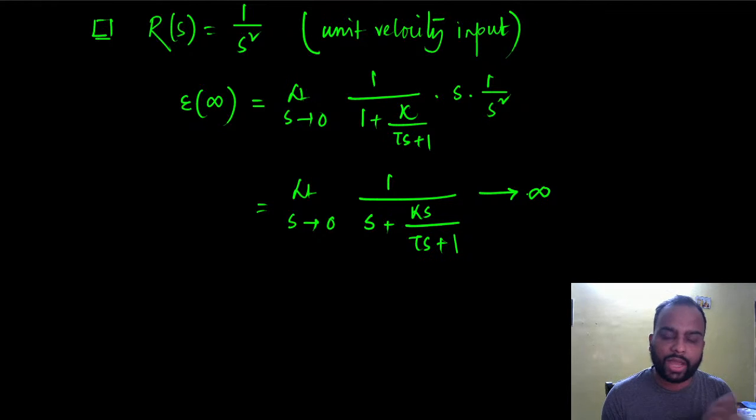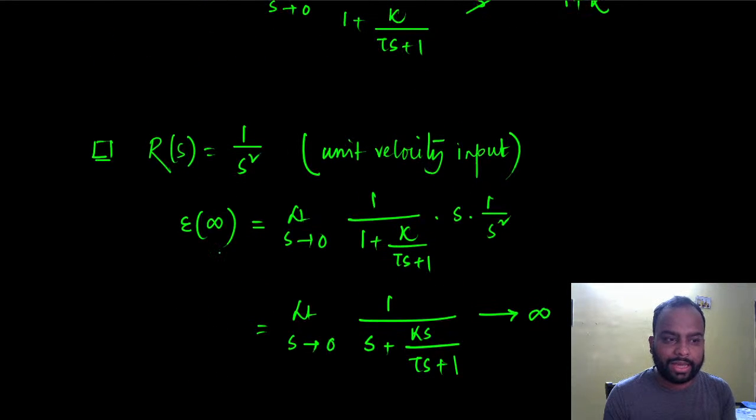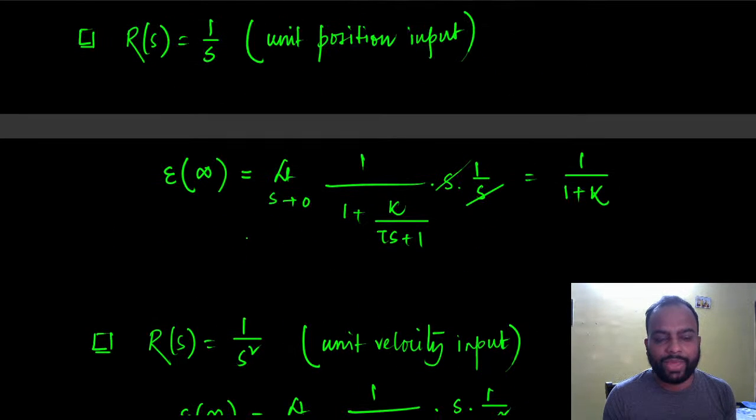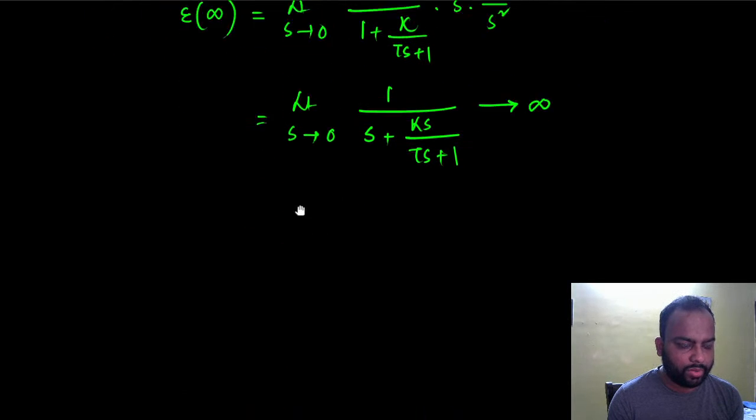So there is hardly anything that you can compare with. Whenever we are talking about errors, we do not really use impulse signals for our discussion. We use step, ramp, and parabolic inputs, and if you consider higher inputs, for example quartic signals or quintic signals, those things can be used. But we are limiting the discussion here, because this is what we really use. Consider a vehicle: either we want it to reach a position, or we want it to go at a certain velocity, or we want it to accelerate. There would be hardly anything more.